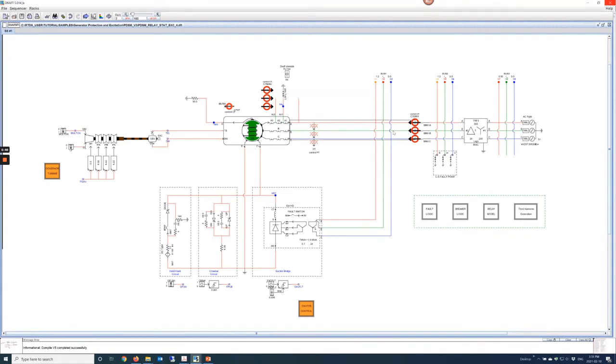When you look at the circuit, you see if my goal is to start this machine from 0 speed, 0 excitation, bring the speed up, bring the excitation up, and synchronize this machine to the network, close the breaker on it. Right at the beginning, when my speed is 0 and my excitation is 0, I have no voltage at this terminal to be able to rectify and excite my field winding.